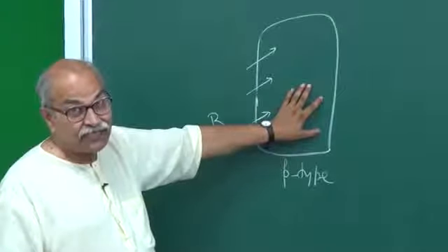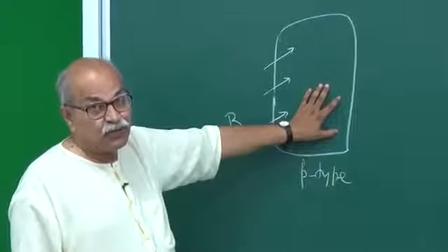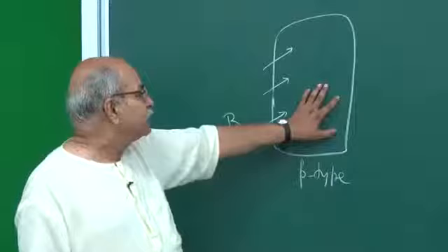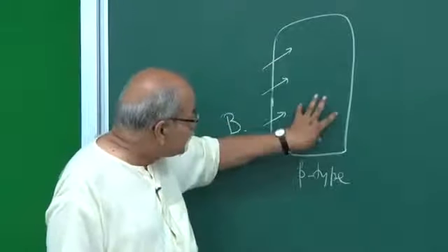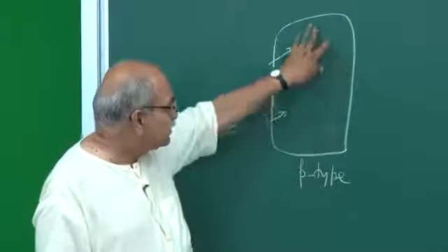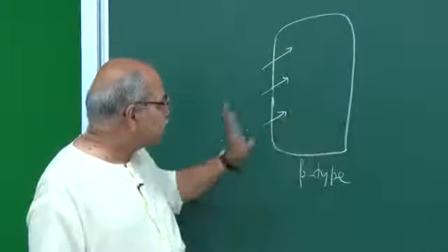Silicon I am taking as our model semiconductor. In any kind of semiconductor you have to do all this processing, and so through very controlled processes, without finally disturbing that crystal structure, you have to put these impurities at those lattice sites.